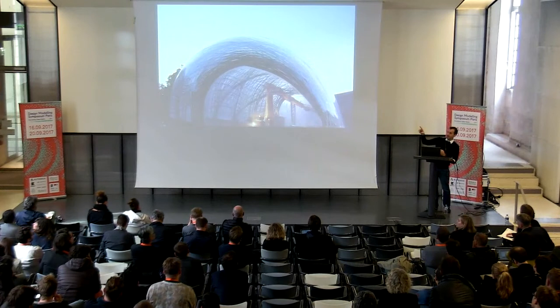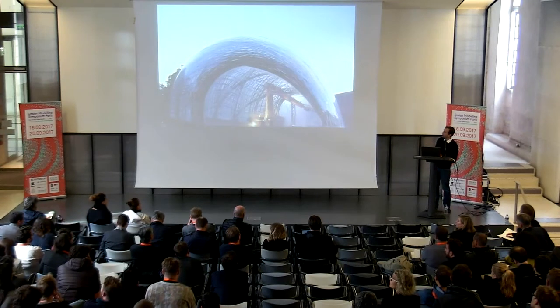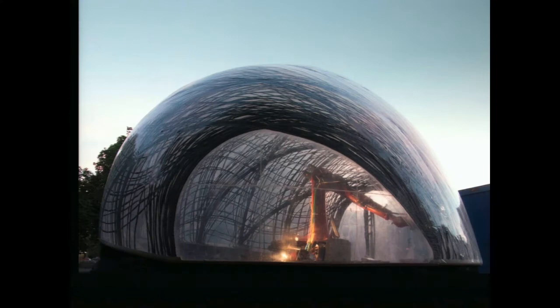As you can also nicely see in the courtyard, you need constant inflation if you want to have it as a pneumatic structure, so we didn't want to have that, but rather we inflate it. Then we have the robot applying the carbon fibers on the inside, and once a suitable stage is reached to actually take all the forces acting on the structure in compression, the robot stops, the air pressure is released, and it works as a compression shell. So at the beginning, the membrane carries the fibers. At the end, the fibers support the membrane as the embedded building envelope.